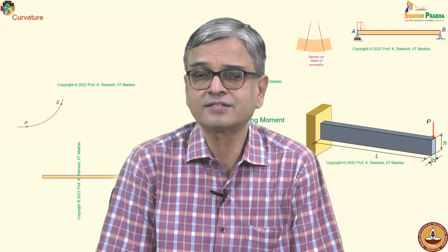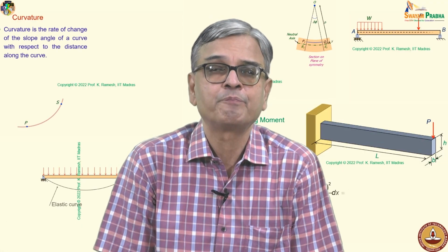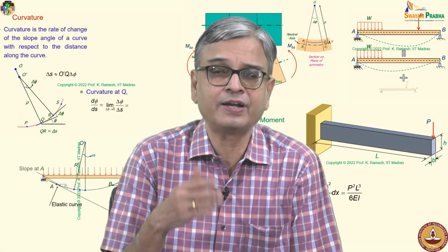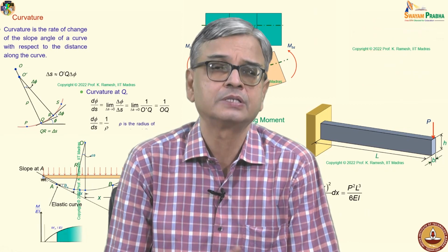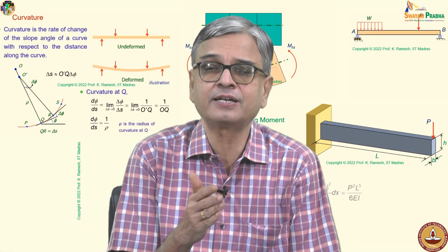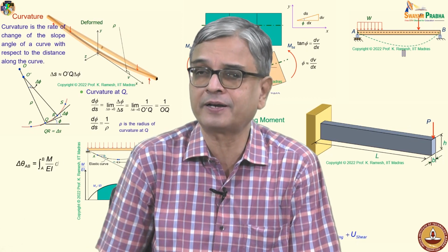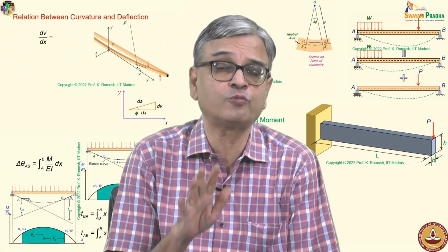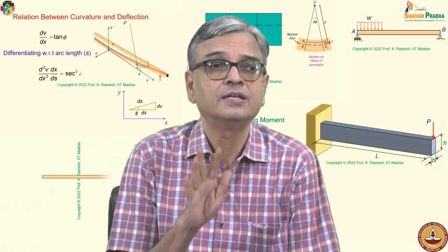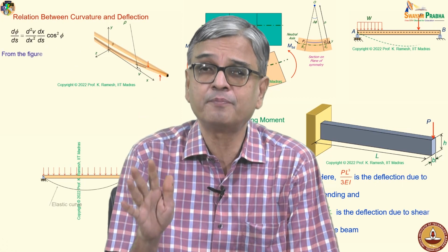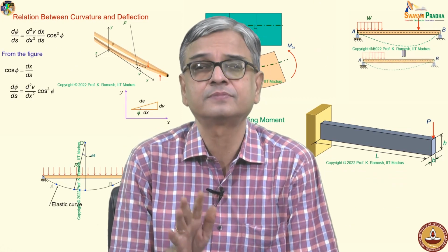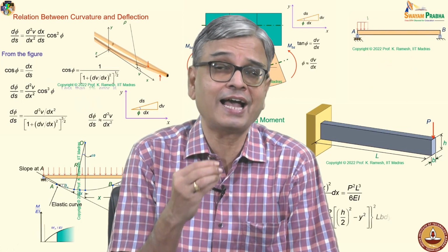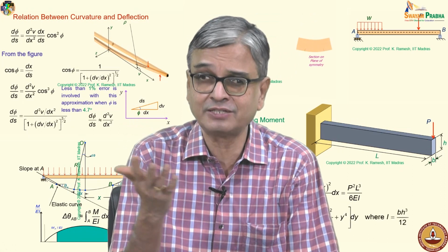Fine. So, in this class, we have looked at what is deflection of a beam. We have looked at you have a deflection as well as a slope, and we have seen slope is nothing but the rotation what we have learnt in strain displacement relations. And here again you develop the basic equation only for pure bending. We extend it for beams transmitting shear force, neglecting the influence of shear, or you have infinite shear rigidity, whichever way you look at it.